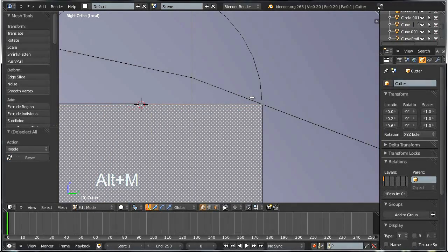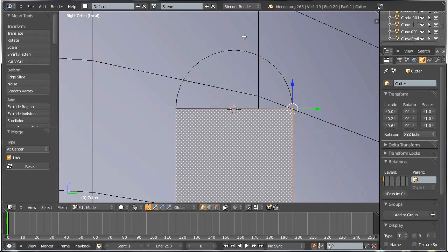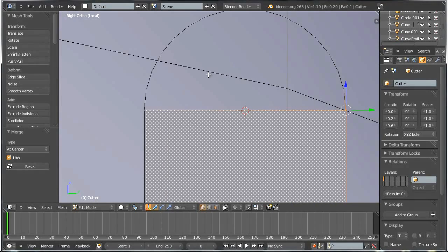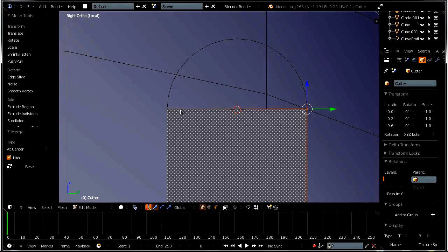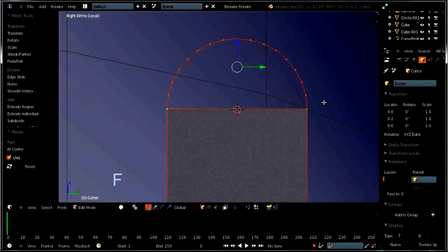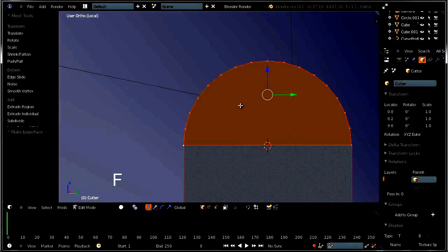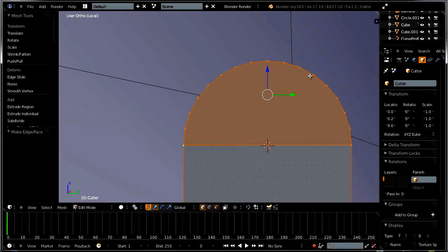Also do the same here for those two vertices. And if we were with the old school, the previous version of Blender with no BMesh, then for filling with faces, this would require the addition of some nasty triangles. But now, as you can see, if I select those vertices and press F to fill them, all it does is fill them, creating an n-gon. All right, so with many vertices.